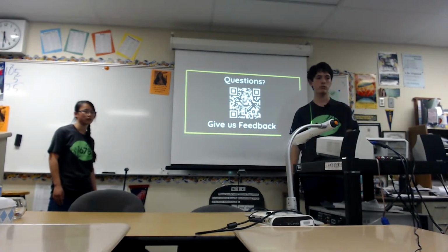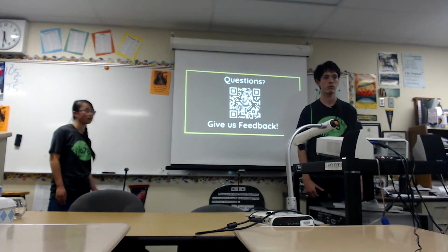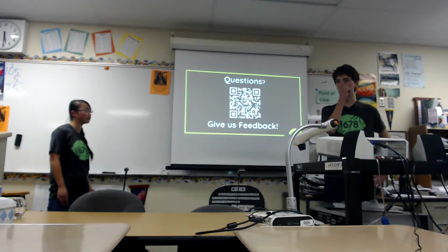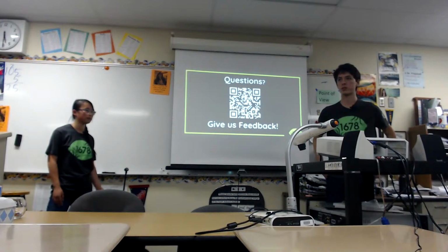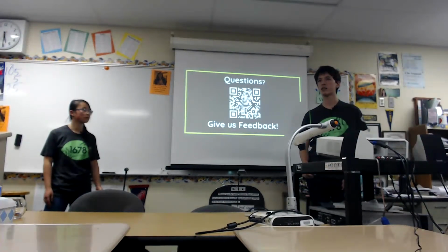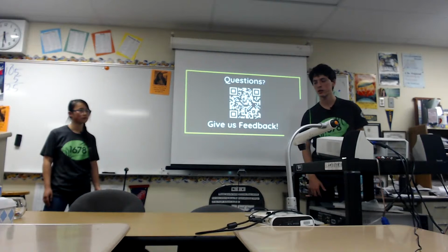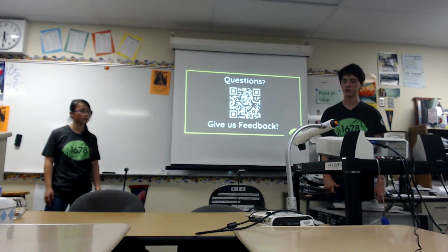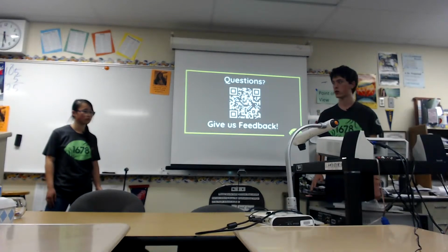You down there. How often is traffic on the CAN bus? It really depends on how many components you're using. If you're using all of your CAN components, I'd say around 15 or 16 nodes is when it starts getting a little bit cluttered. So try to keep it around 12 to 13, which I think was what we found worked the best.